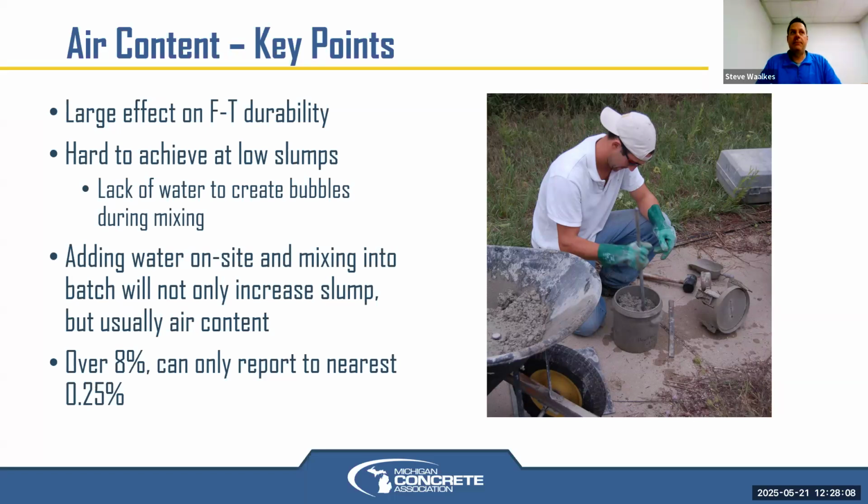So it's a great lab-based tool, but the repeatability and reproducibility in the field and for QA and acceptance have not been proven out to be accurate enough. But if I were an admixture company developing a new air entrainment admixture, I would have one of those in my lab, and once I got my new formulation, I would want to see how stable it is over time and at these different pressures. So it's a great tool. It's just not a good QC or QA tool in the field.